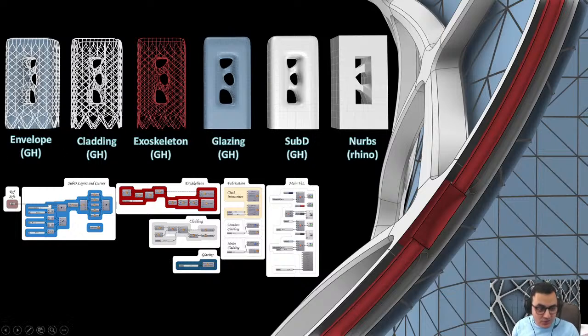This is basically what I did. This is the full envelope. I did the cladding. Let me start from the right. This is the NURBS, the Rhino part. After that, I input it into Grasshopper to make it a mesh and to extract the sub-D part from it. I turned it into glazing. I created a grid from the sub-D and used it to create the structure and the cladding.